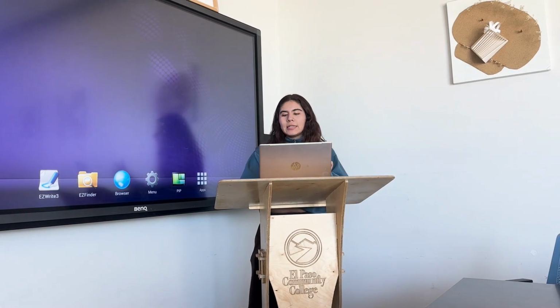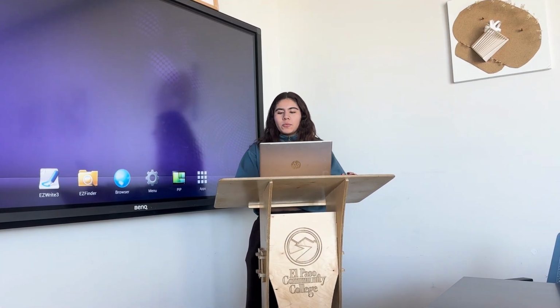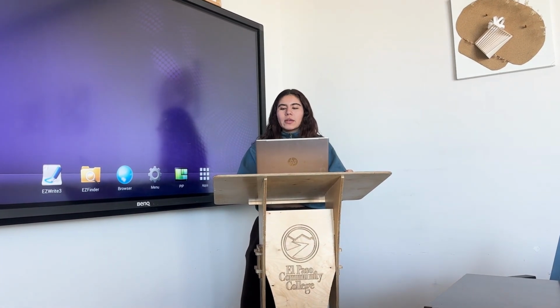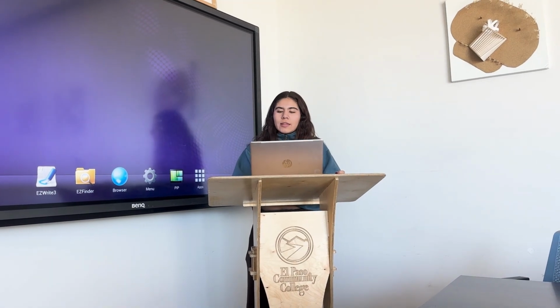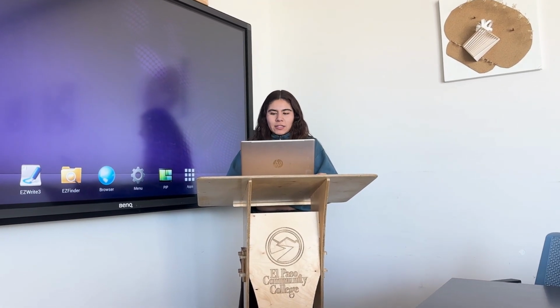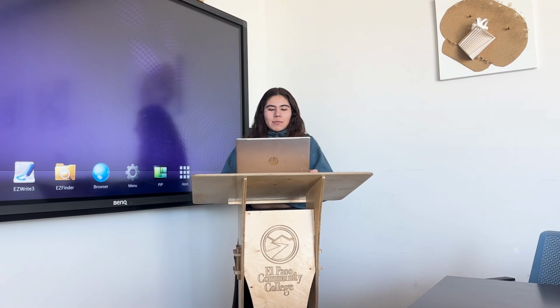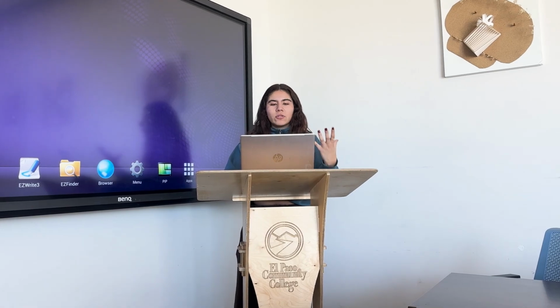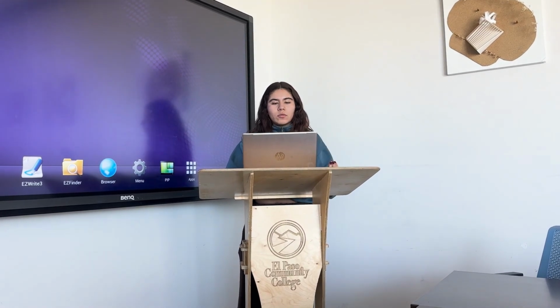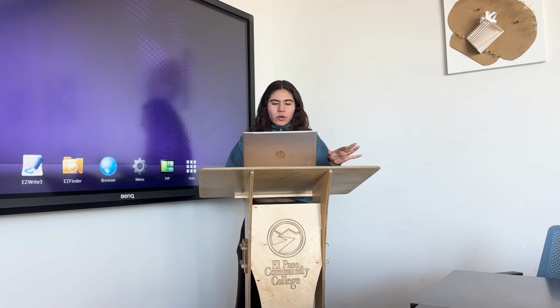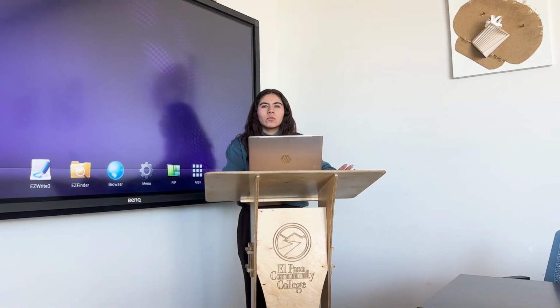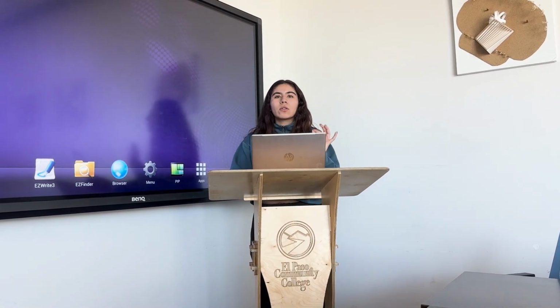The first one is the external flashings to prevent moisture from penetrating into the wall at vulnerable exposed surfaces. The second one is internal flashings. By this, I mean that they catch water that has entered the wall and drain it through weep holes back to the exterior. Another term that it's very important for you to remember is metal coping.